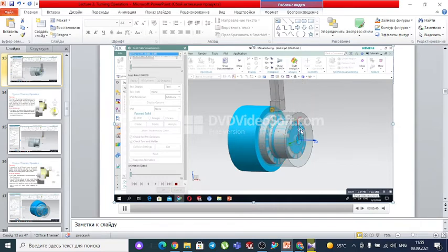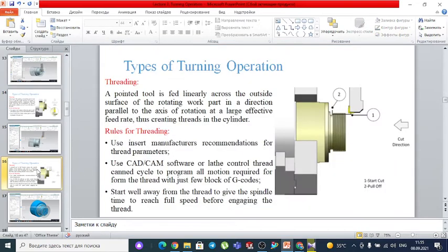You see the final shape is already obtained with the finishing operation. I just used one layer for the finishing, and while programming, you can use several layers. So the final shape is almost obtained. Now we have to do the other operations in order to obtain our element.